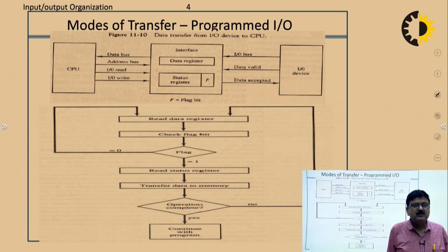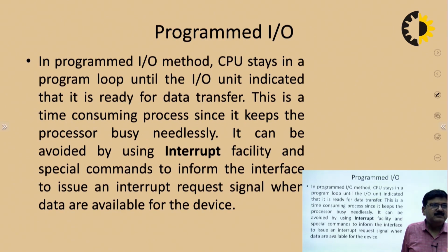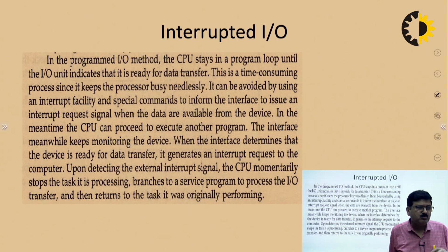To overcome this issue, we come with another technique, interrupt input output, in which the duty of the device is to send the interrupt. Basically, if the CPU gets an interrupt, it holds the current working process and transfers the control to the requesting device which initiated the interrupt.